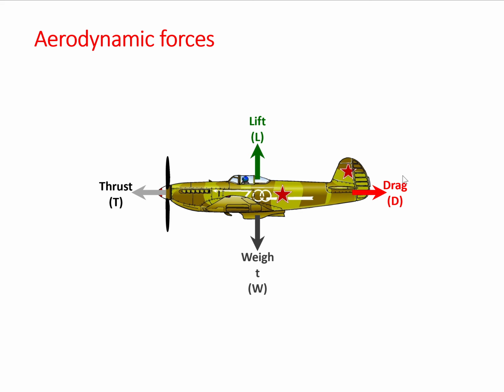But having drag is not useful in most scenarios because it is essentially pulling your aircraft back where you want to go forward. So our goal in aerodynamic analysis, at least in aircraft aerodynamic analysis, is to maximize lift while minimizing drag, which essentially means that we want to maximize the lift over drag ratio. And in this lab, we will only care about these two forces, lift and drag.